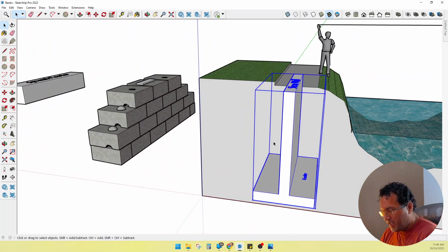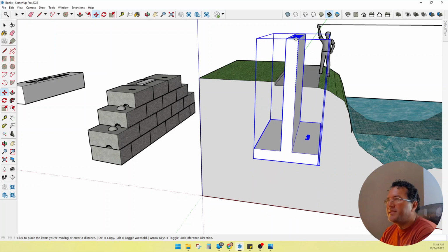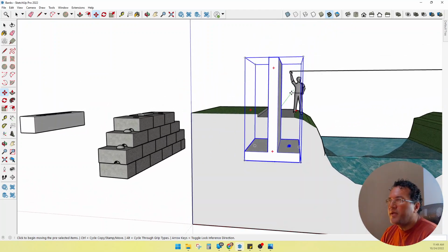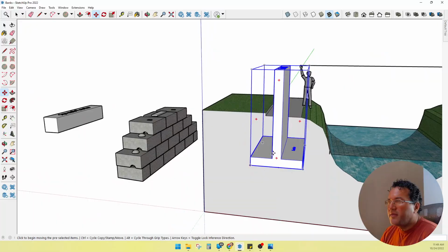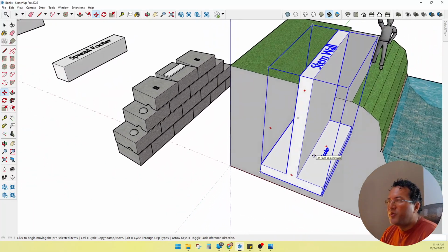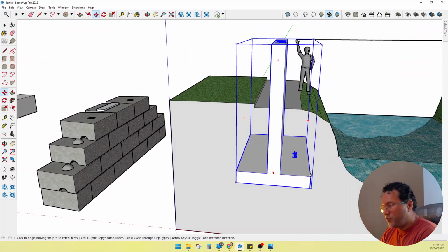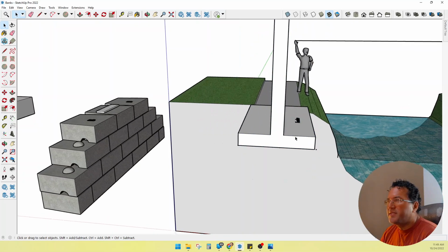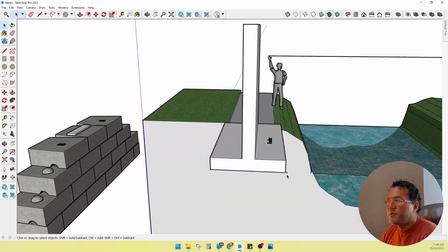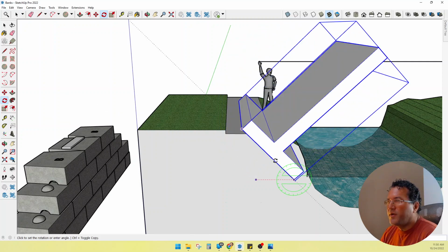Now the stem wall, we can put the top of the stem wall flush with existing grade, or we can raise it up in order to gain elevation as well. So there's a couple of different options with that. This footer here does have to be pretty deep in the ground. You can't have it at grade. You can't have it super high up where this is sitting way up over here, right? I have an excellent video that talks about the abutment toe. The abutment toe on this one would be right here. If we do that, then we run the risk of this entire abutment wanting to rotate over, right? It wants to just topple over.